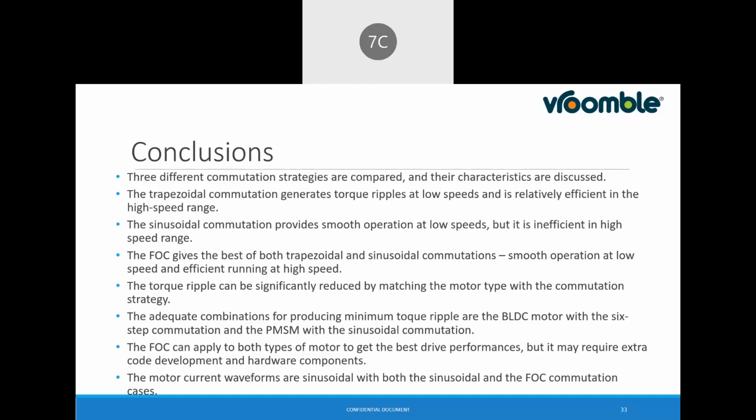That is the basic difference. So we call it BLDC, but it is a PMSM motor or PMAC motor, permanent magnet synchronous motor. Ultimately it is AC after the inverter, but the power source is definitely DC. Whereas in Tata Nexon, they were using an induction motor. They have changed now, the induction motor is changed from the DC.